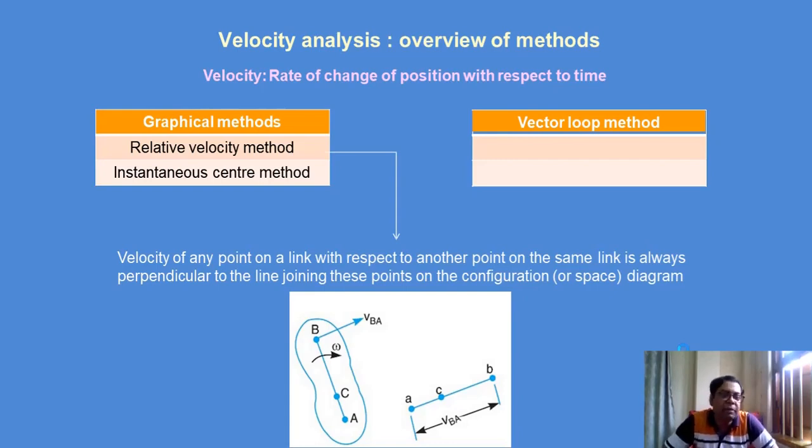Point A and B indicate that with respect to a static point A, point B has a rotary or oscillatory type of motion. So when this type of motion occurs, point B definitely has a linear velocity component which acts perpendicular to the direction of the link AB.